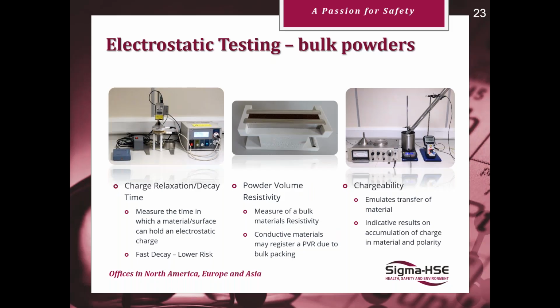Chargeability on the right-hand side is basically just simulating a movement operation of a material through stainless steel pipe or whatever is appropriate to the actual process. And it just provides indicative results on any potential accumulation of charge in a material and the polarity of that charge.